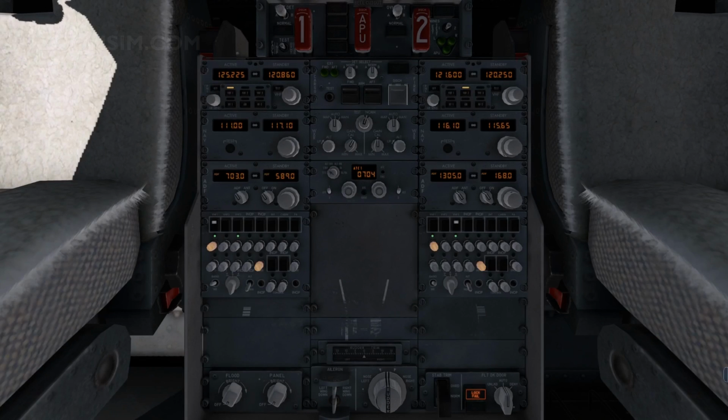Radio tuning panel, set. Verify that the off light is extinguished. The offside tuning light is illuminated when the radio normally associated with this panel is being tuned by another radio tuning panel, or the radio tuning panel is being used to tune a radio not normally associated with this radio tuning panel. VHF communications radios, set. VHF navigation radios, set. Audio control panel, set. ADF radios, set. Transponder panel, set.